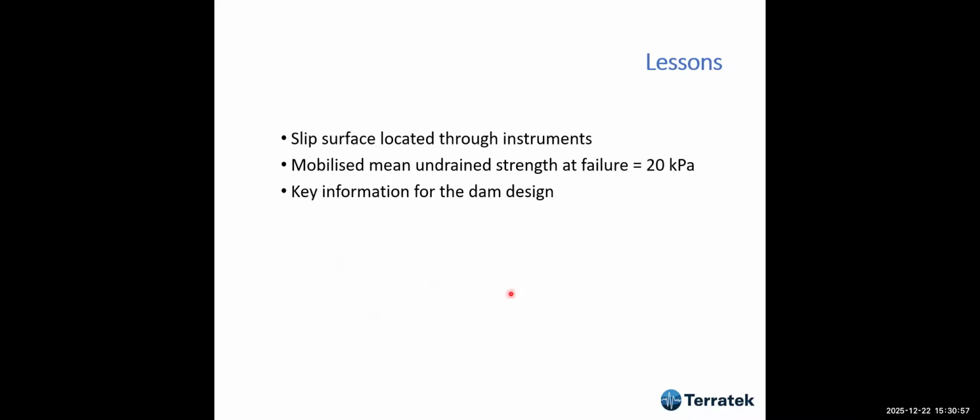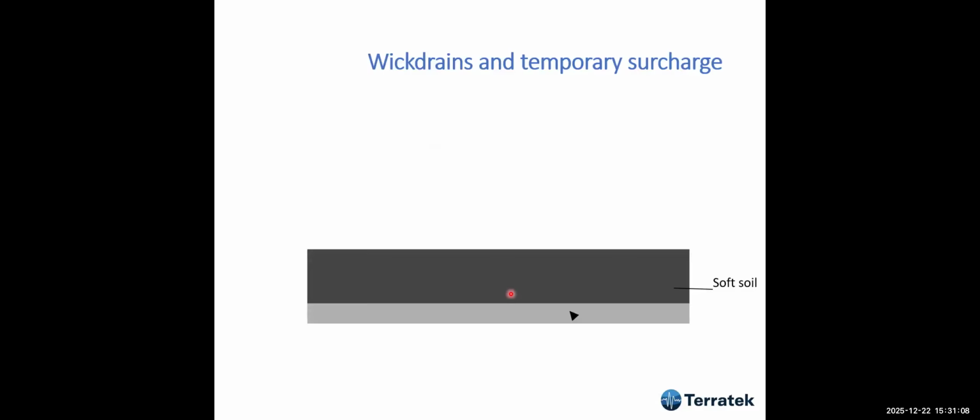And so these lessons were very important for the design, and the berm was not too long because they could use these values. Okay. Later on, we had some projects with wick drains and temporary surcharge, which worked quite well.